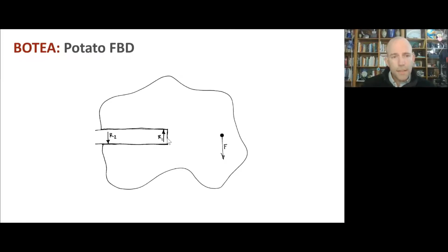And the other thing to see is that the lever arm for that friction force is going to be small compared to the lever arm, at least the potential lever arm of these normal forces. And so both of those two things put the friction at a disadvantage for overcoming the moment created by the rope.